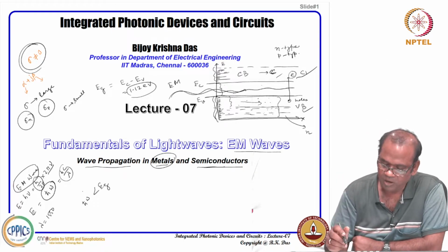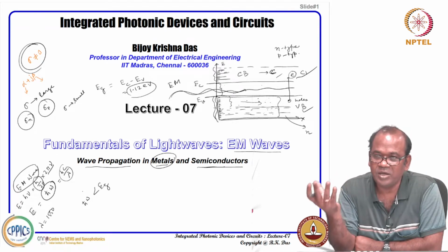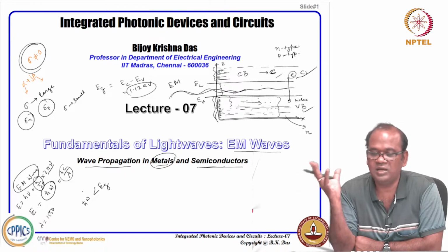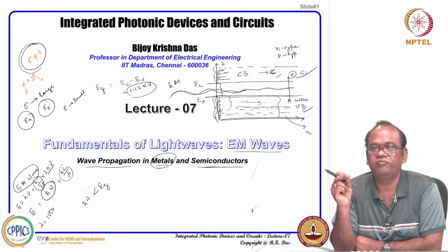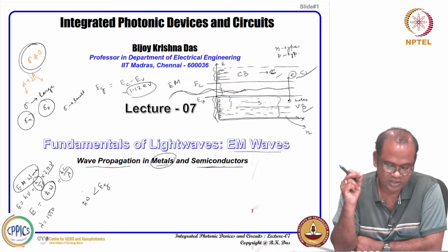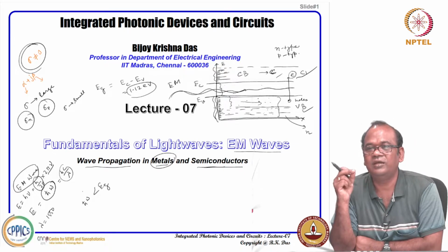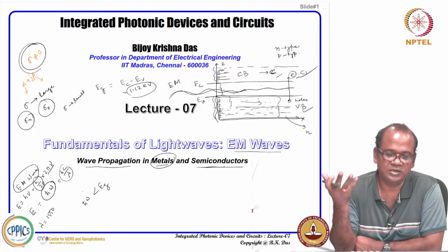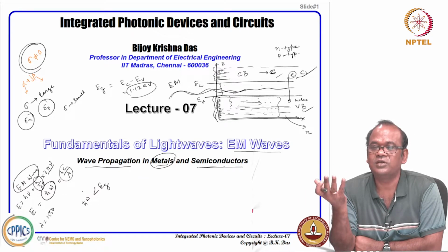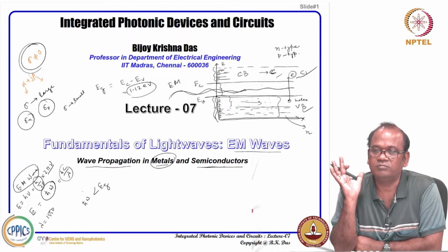Okay. So, even though it is a semiconductor like silicon, germanium, gallium arsenide, if it is completely undoped, intrinsic material, and you consider any electromagnetic wave as a stream of photons, and the photon energy is just less than the band gap energy, then that particular semiconductor, it can be silicon, gallium arsenide, or germanium, can be considered as just a lossless dielectric medium.